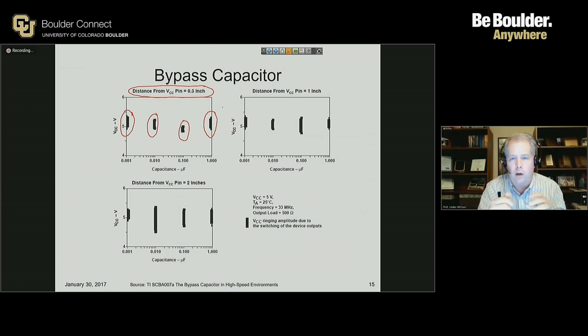One thing I want you to all recognize is that when we talk about components, especially these passive components, capacitors, resistors, or inductors, the component is called that, a capacitor, resistor, or inductor, but it has the properties of all three of those. So a capacitor that I put in the circuit is not just a pure capacitor. There are inductance impacts, there are resistive impacts. And for particular uses of those components, we have to be aware of those other characteristics, not just the pure capacitance.